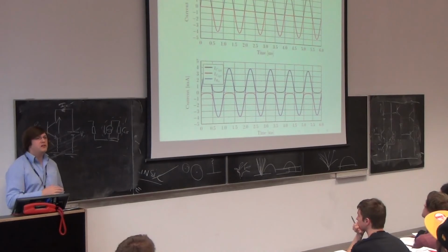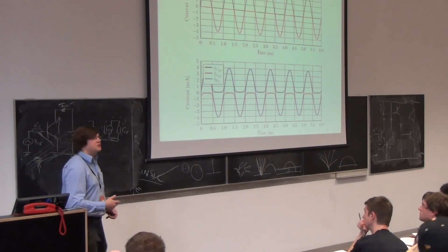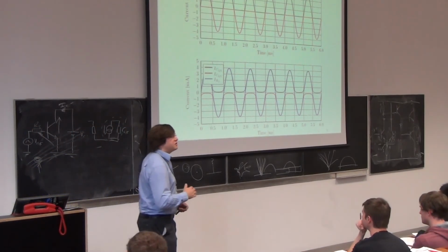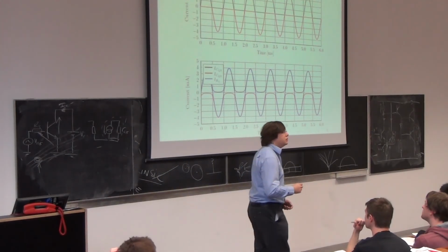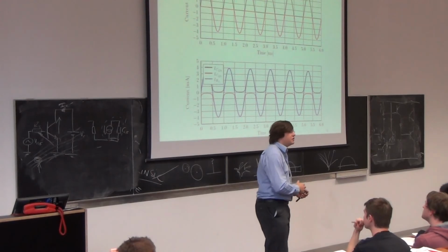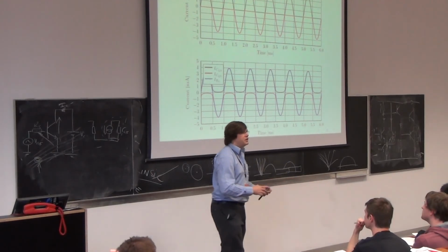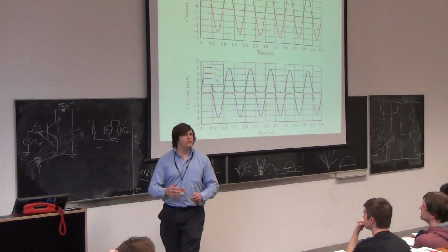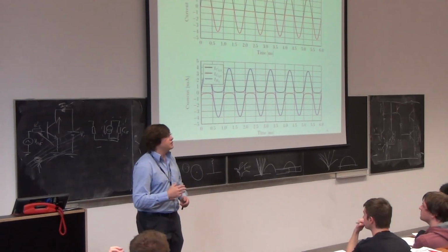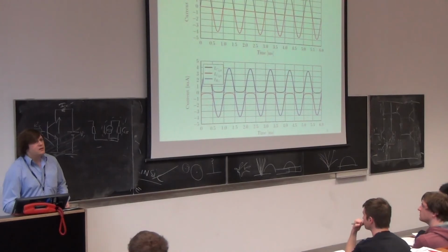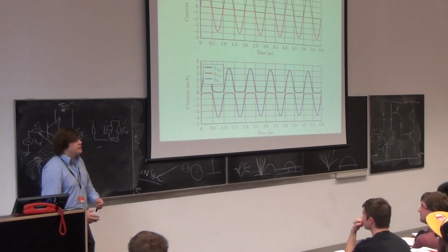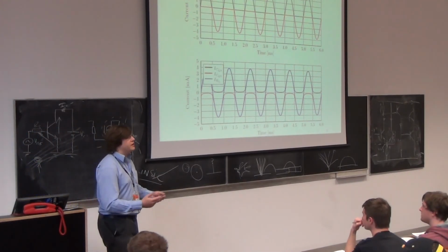So how much I bias those transistors on determines the quiescent current. And the more I make the quiescent current bigger than the signal, the smaller the signal starts to look. I'll transition from a large signal arrangement into a small signal arrangement by virtue of the quiescent current becoming much bigger than the signal. So this is how the quiescent current, the class of the amplifier and the angle of conduction are all bound up together.